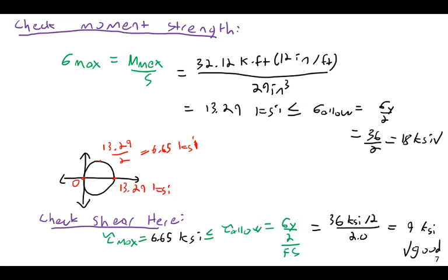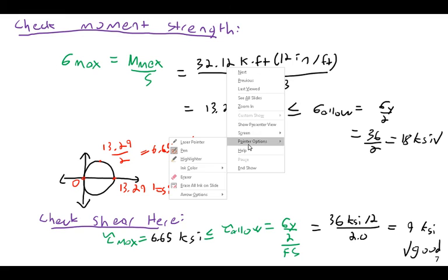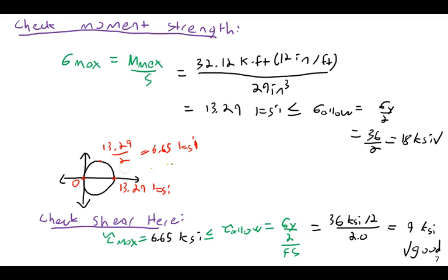So essentially, to review here, at the location of max moment, let me just recap. At the location of max moment, check normal stress and shear stress. Okay, so now we need to move on to a different location.